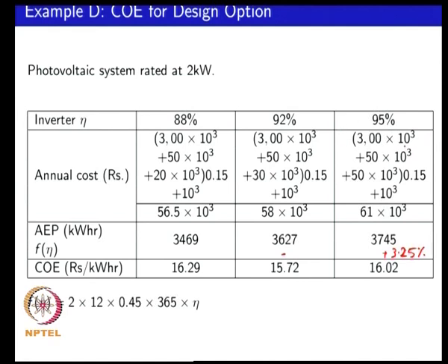So, there is benefit from other balance of system too because of the power electronic unit, because it is actually sitting closest to the point of common coupling where the energy is being sent out. In this particular case, even though the cost of the inverter is low, you are actually producing 4% lower power, in which case to get the same 2 kilowatt you need 4% more panel area. So, your panel cost would go up proportionately.